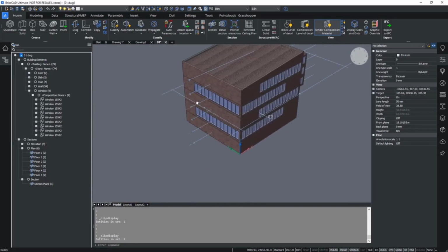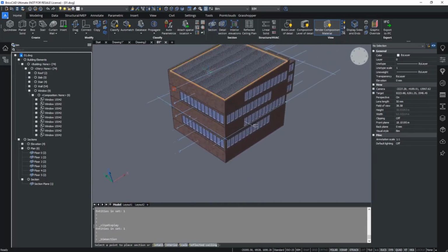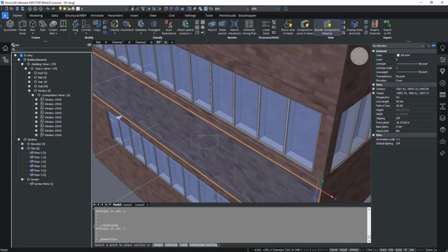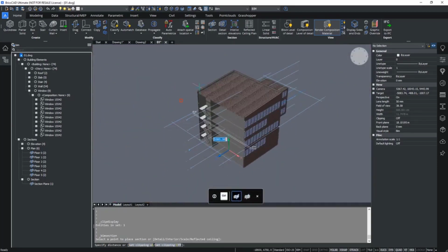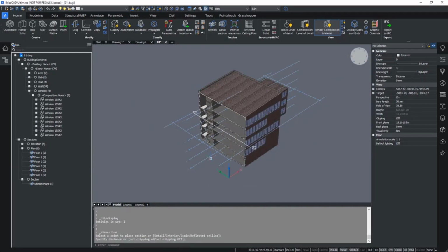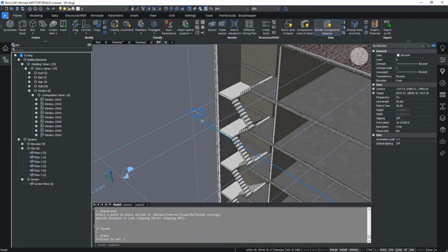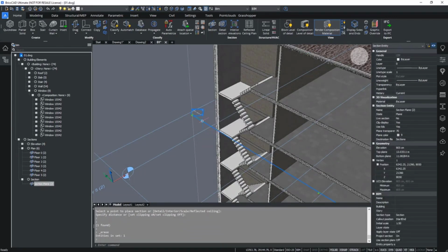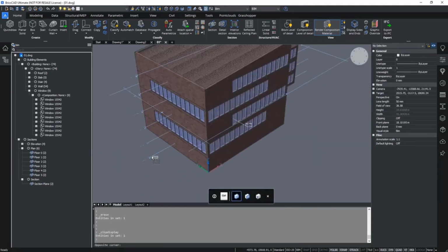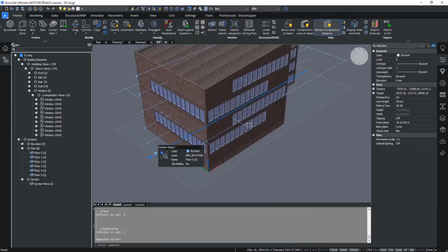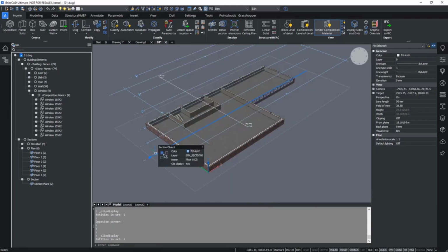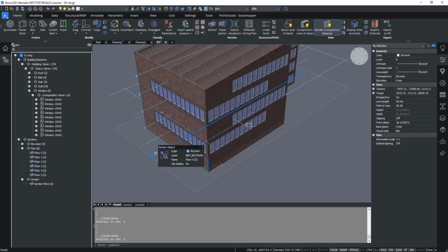and the BIM section tracker that is used while creating your section also delivers you information about the viewing direction, which is the arrow, and the plane where it will be cut, or which orientation of the plane your section will have. And then you can delete them by just selecting it and pressing the delete button. You can clip and unclip them by double clicking them.